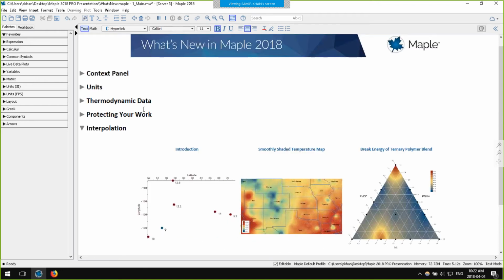So there are many interesting applications of unstructured irregular interpolation in science and engineering. One application is in FEM, finite element modelling. A single FEM simulation might take a few hours to run, so it's far more efficient to run a limited number of FEM simulations and then use interpolation techniques to predict the response at intermediate points, and that's typically known as meta-modelling.